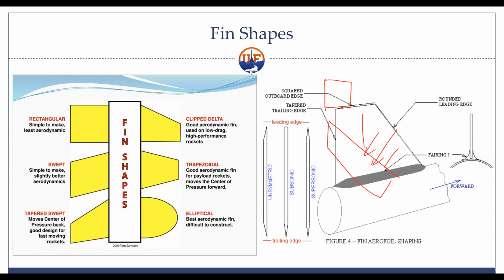I didn't do the vectors very well. Going against the fin like that, and then another one going that way. It actually reduces the wave drag on the fin, and so less drag as a result. It also improves the stability for the converse reason, because there's more lift produced as a result.